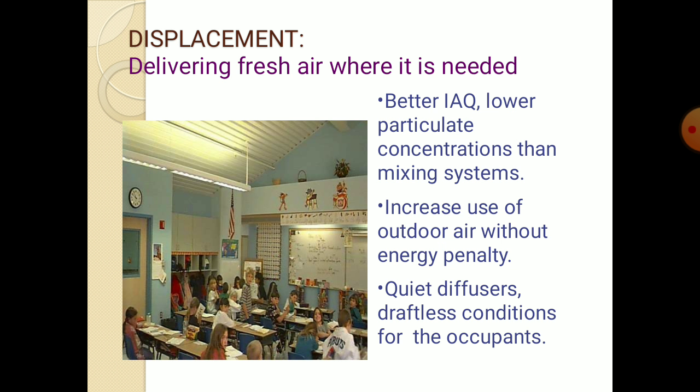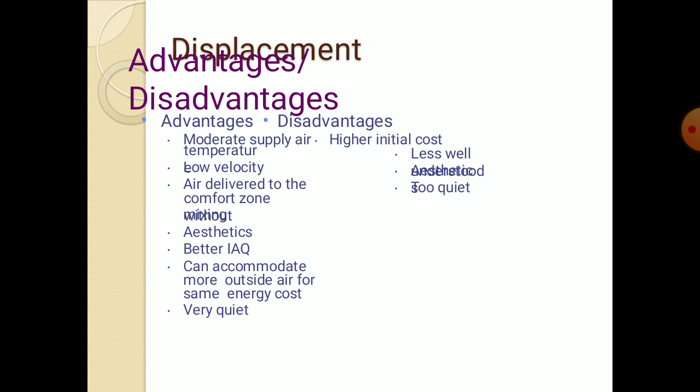This displacement delivers fresh air where it is needed. So lower particulate concentration than any mixing system. Displacement increases use of outdoor air without energy penalty, because tremendous amount of energy can be saved if we do such things. Quiet diffuser, draftless condition for the occupants.